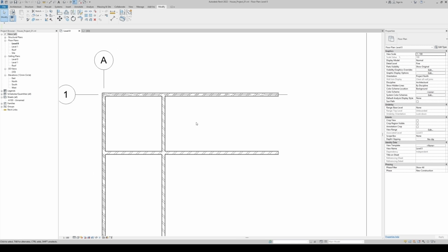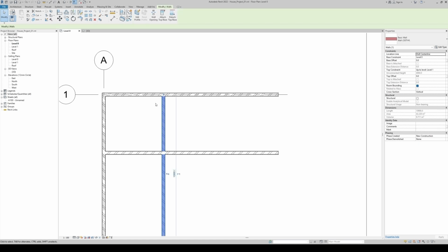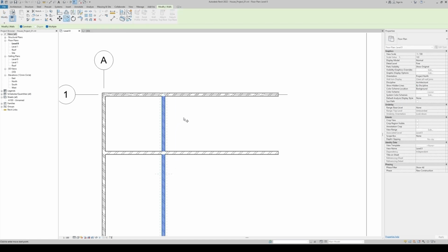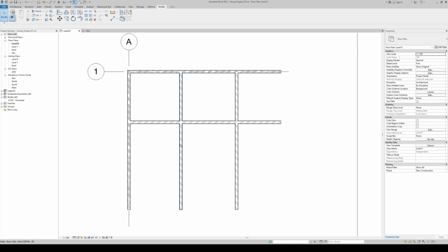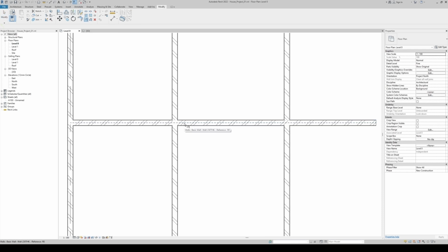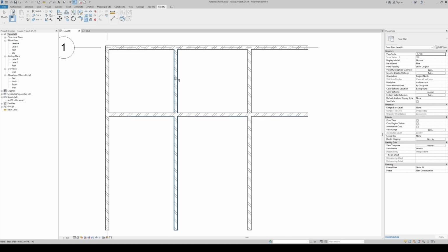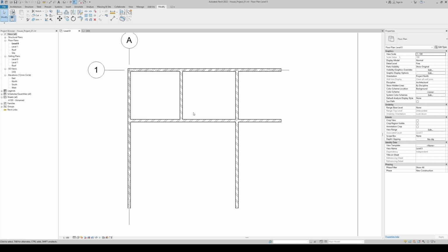Let us create a few more geometry. So select your wall, go to copy and just create simply a room. Now, if you want to trim this wall, you can pick the trim or extend command from here. Select the center or face of the wall and just click on the part you want to retain. So here is your wall just trimmed based on this line's reference.